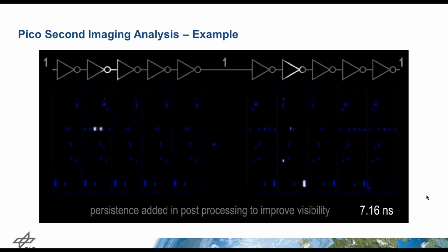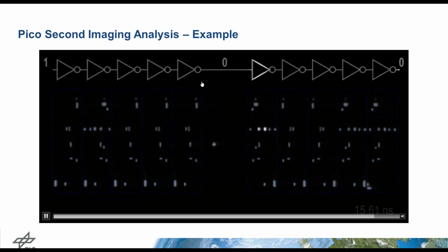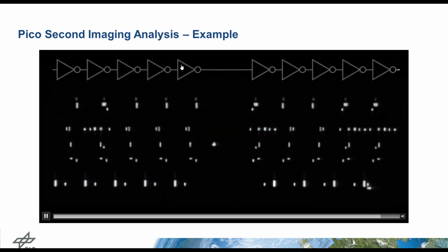Here we rounded the precision to 10 picosecond, but it's sufficient. So here on the top, we have the inputs, and at the bottom are the outputs of such a logical element. And what you can see here, we now have the big one emitting. So here's the small one. These are the output transistors. It's a PMOS and the NMOS. You can see, and they have to change. For one logical element, it has the big one. For the next, it has to be the small one, because the logical state is changing.